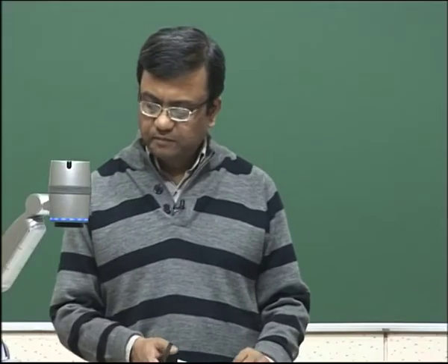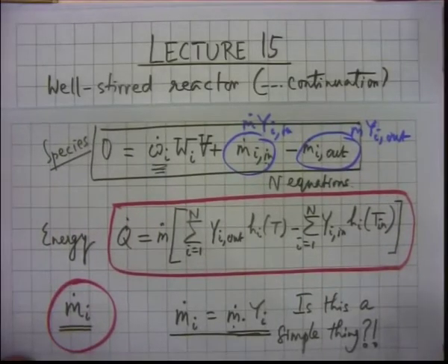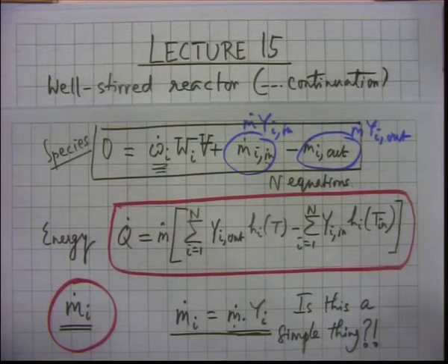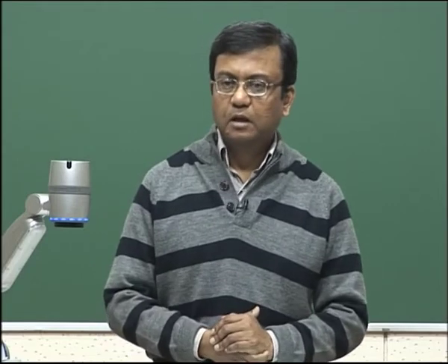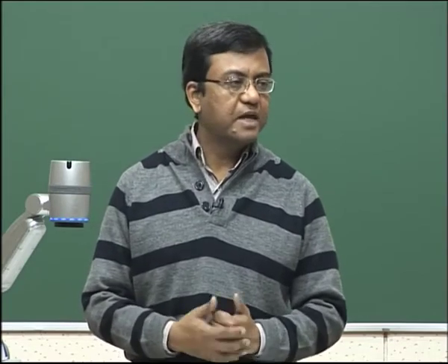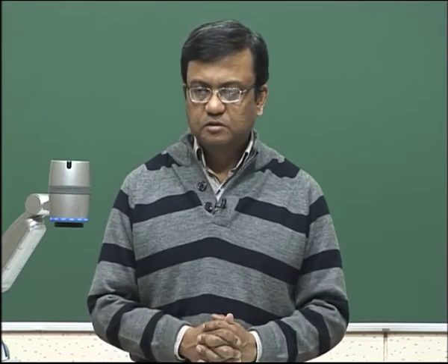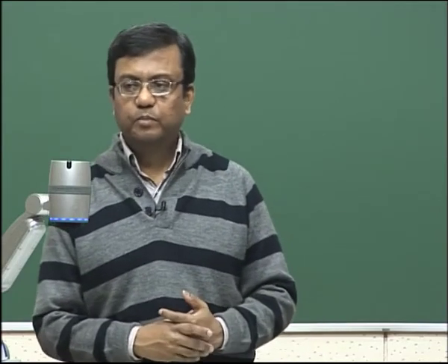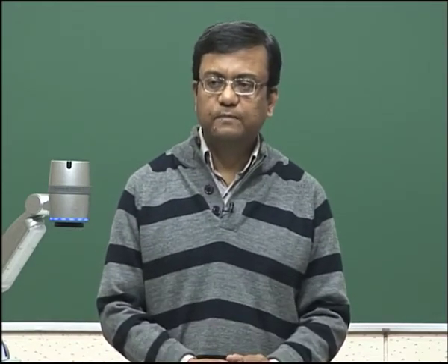Welcome to lecture 15. We were discussing the well stirred reactor yesterday in lecture 14, and these are the equations that we had. So, remember that this is now a vessel in which there can be one input stream or multiple input streams, carrying fuel and oxidizer typically, and then the fuel and oxidizer react inside the chamber. The products are formed, temperature is raised to some higher value, and then the products at that higher temperature and a different chemical composition will exit.